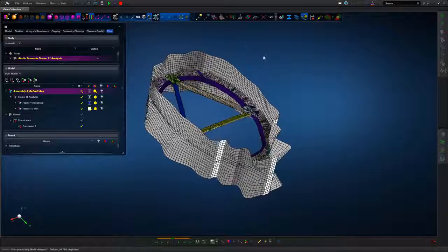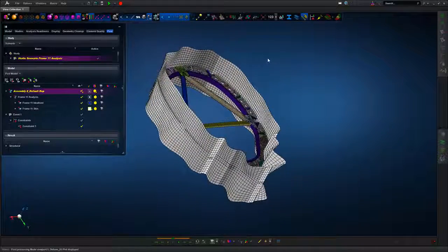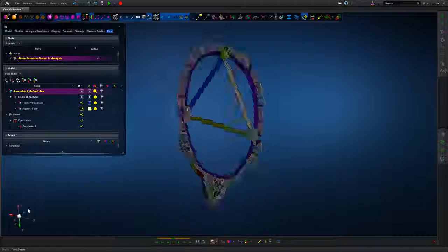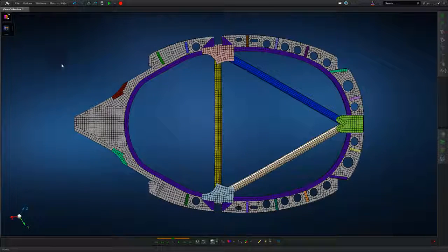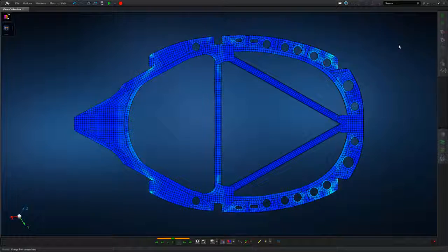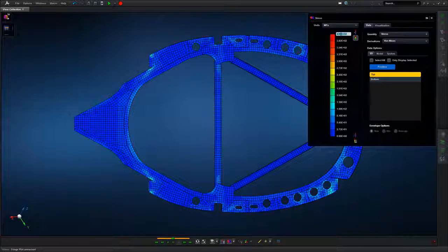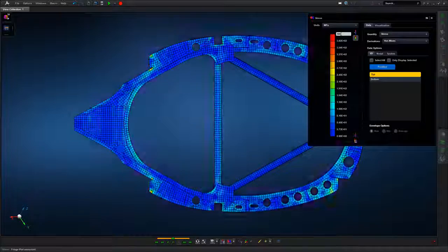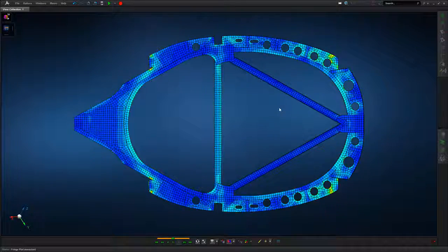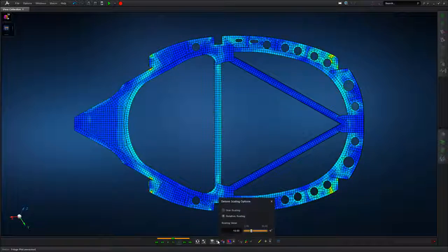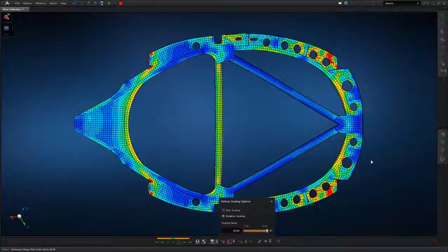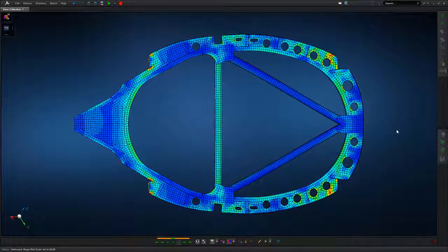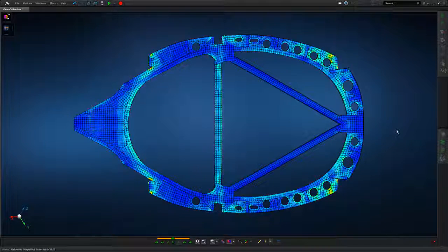So running through that, and again, we've got a very thin fuselage. So this is just an example, but it highlights the way the load transfer is moving into the fuselage frame. So taking the fuselage skin assembly out of view and post-processing based purely on the overall original sub-assembly, we can see by looking at the von Mises stresses and putting in a 200 MPa limit, which might be appropriate for the stress limit that we've got defined for the structure, and we can look at the major response and how the load is being tracked or distributed through the structure.